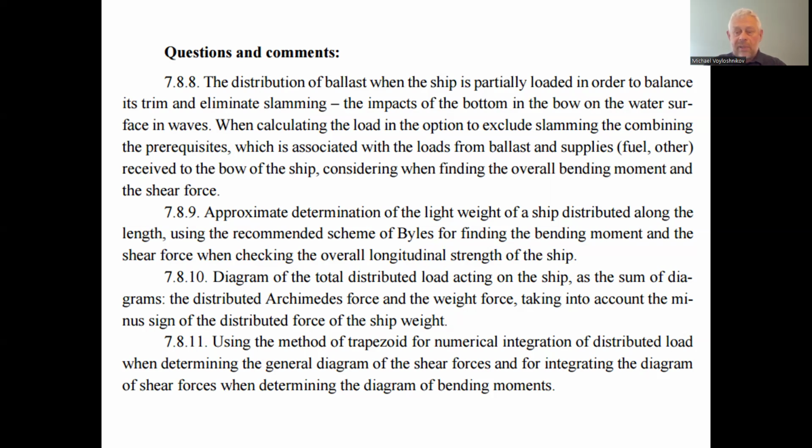So, having the distribution of the external load, we can find the shearing forces as the integral of the distribution of the load on the ship, as the difference of the Archimedes forces and the load forces of the cargo and the ship combined. After that, we can find the integral function, which will be the bending moments, by the reference variable of the ship length.